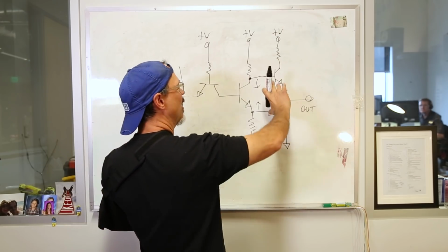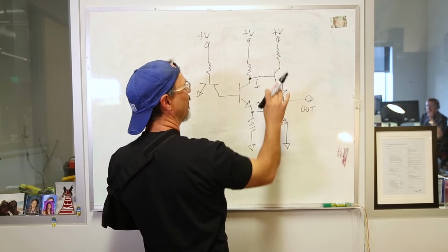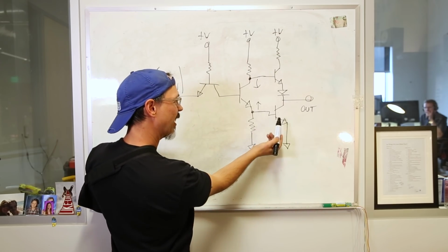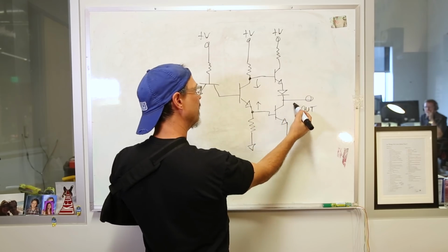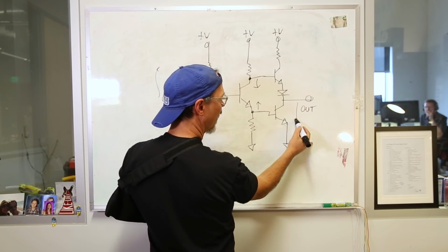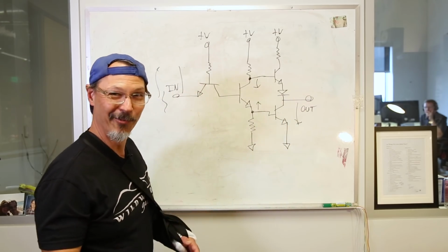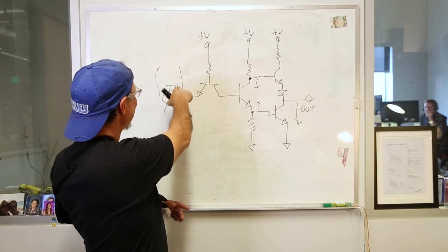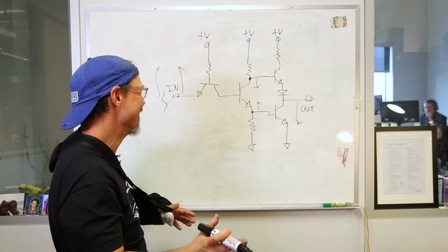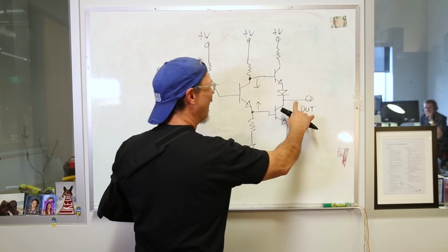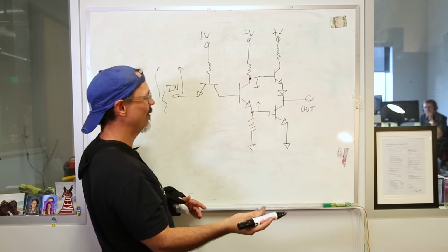Now what happens is, when you bring these 2 points close together, this guy will turn on and this guy will turn off. When this guy turns on, small resistance here, that value goes low, right? Did that work? I'm gonna look back and see. Yes, I said high the first time, low out. Hooray, I did it right this time. Now when you do it the other way, it goes the other way, right?